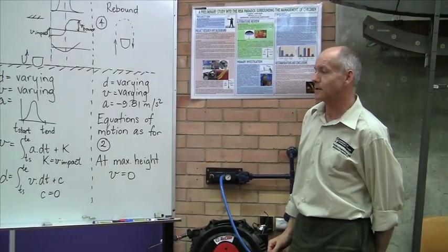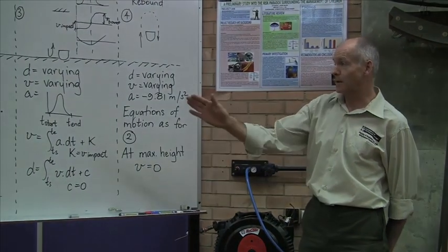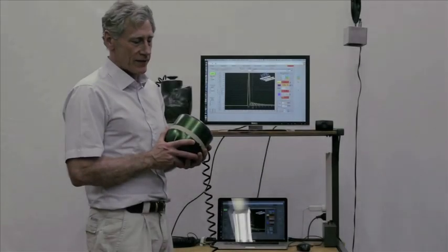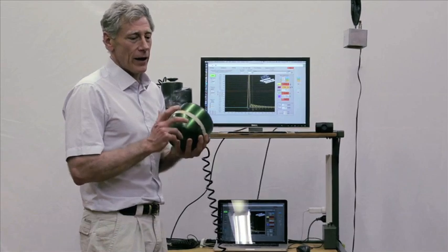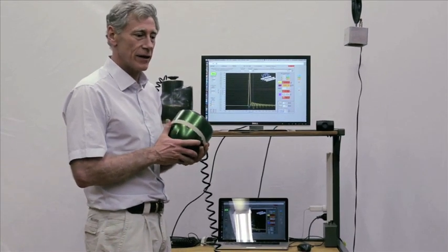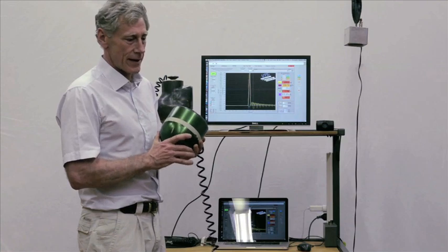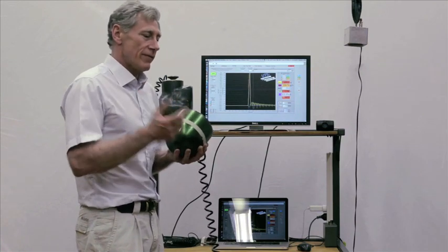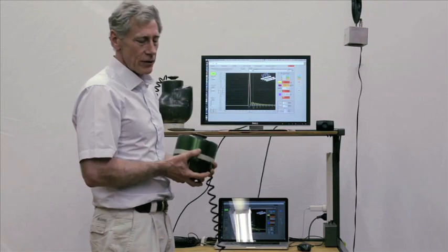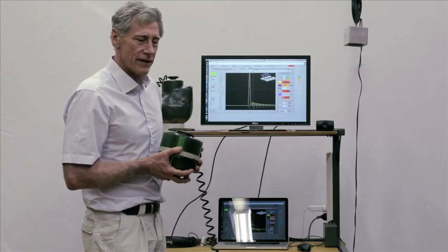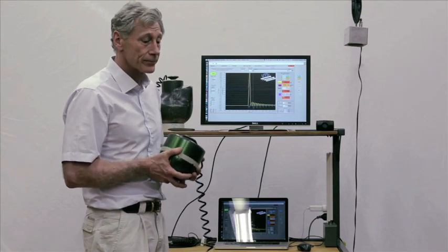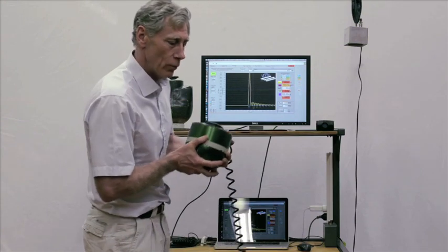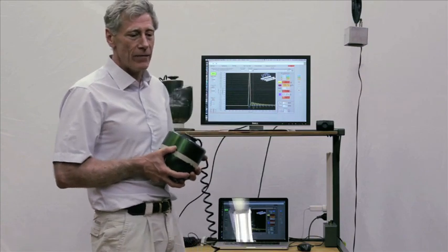And that's how we use the equations of motion to calculate what's happening at various stages. In children's playgrounds, we have two pass-fail criteria. We have 1,000 head injury criteria (HIC), a unitless number, and we also have the 200G. So if a drop exceeds 200G or it exceeds 1,000 HIC, it's a fail. What is it? How do we get these numbers and where do they come from?